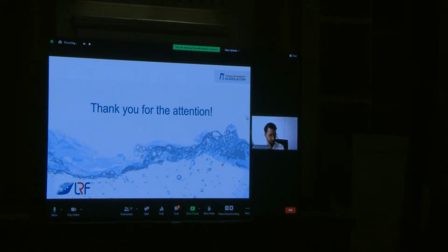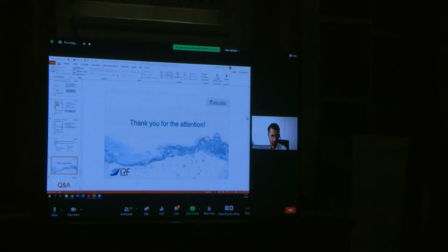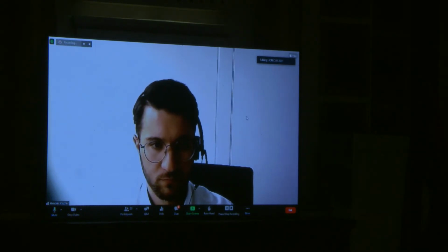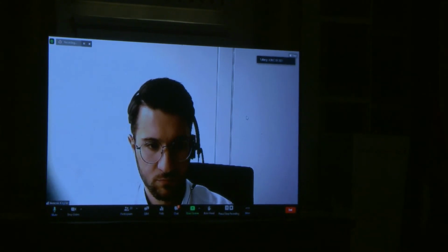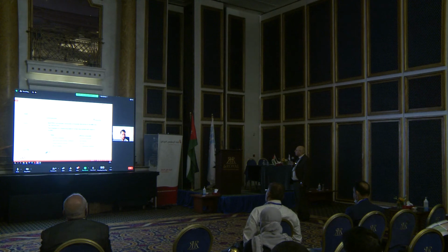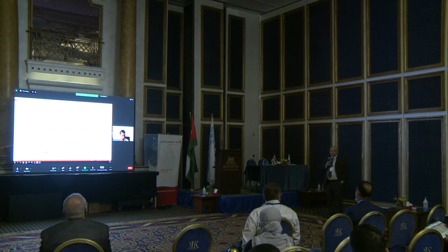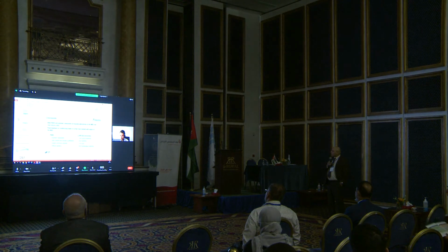Thank you very much, Hendrik, for this useful presentation. Actually, this is very interesting for the desalination industry as a new material, new tube materials. I would just like to ask about the applicability of such polymers at high temperatures. You know, in the desalination industry, the working temperature is about 200. Can these polymers work at these temperatures? PEEK can work at these temperatures. Yeah, it is a high performance polymer. For the polymer composites, we cannot use polyethylene, that's clear, but we have another project where we test PPS, for example, composites, so polyphenylene sulfide, where we can go up to 150 degrees.